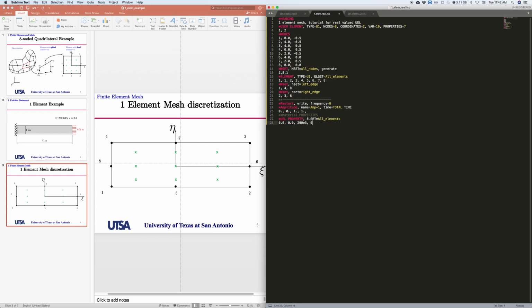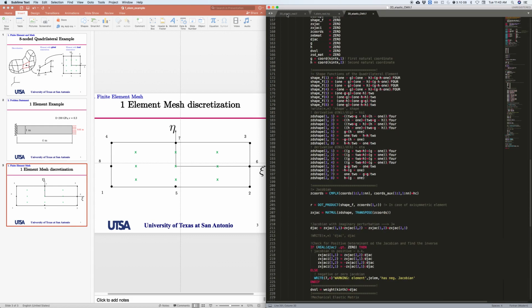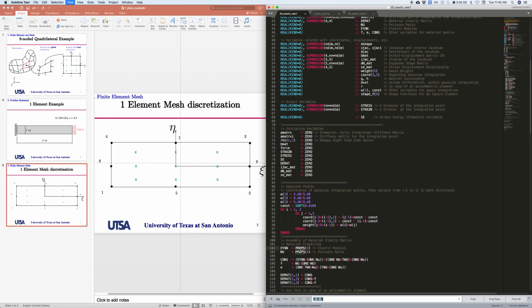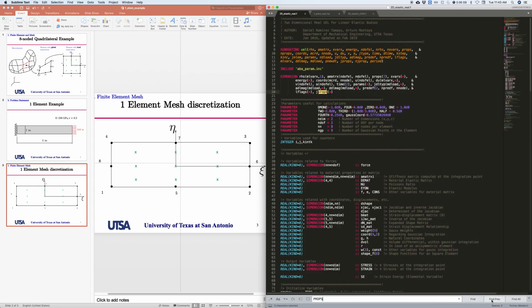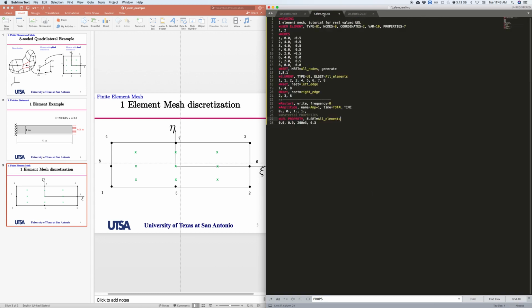And then the Poisson's ratio is gonna be 0.3. Okay. And those are the only 4 variables that I need, right? Let's check here in my UEL where else I have these props. So I'm just gonna look here. So I only work with the props 3 and 4. So those are the only 2 properties that I care about.